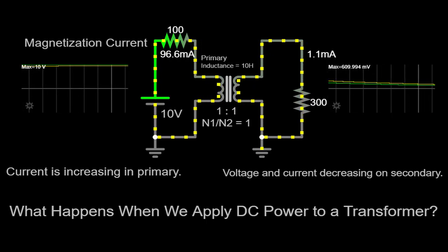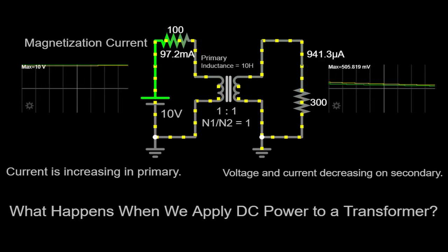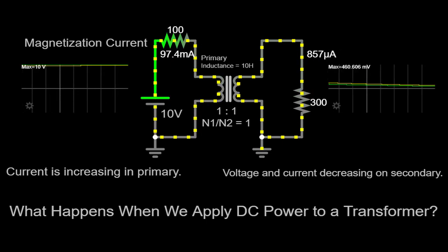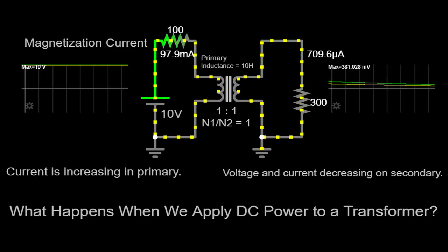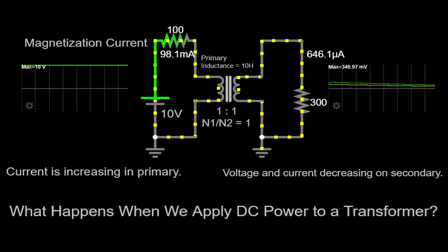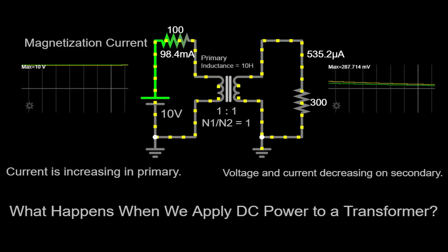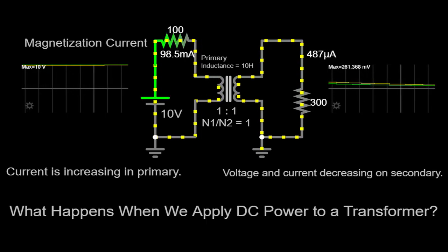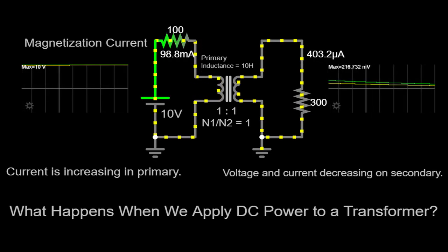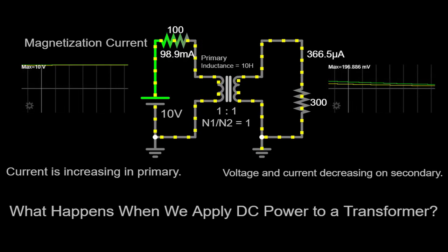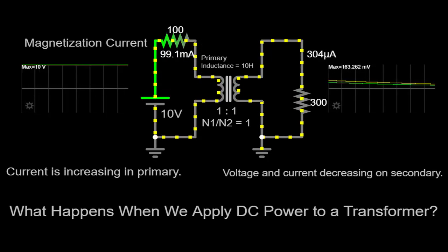its failure. Applying DC to an isolation transformer undermines its intended purpose, resulting in a loss of isolation and safety features. Isolation transformers are meticulously designed to provide electrical isolation, shielding both devices and individuals from hazardous voltages. However, when DC is supplied, the lack of isolation compromises safety, exposing equipment and individuals to the full voltage present in the system, thereby creating significant safety risks.